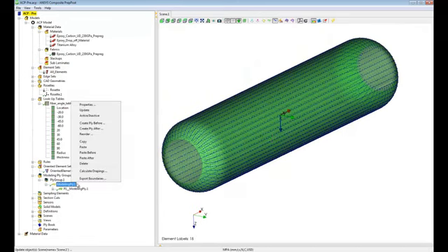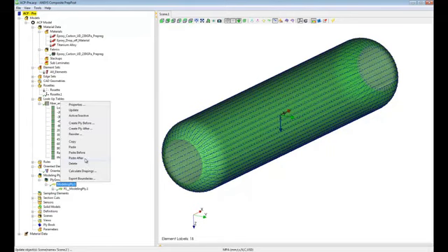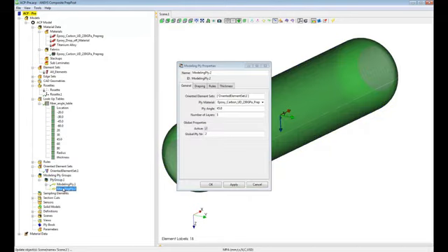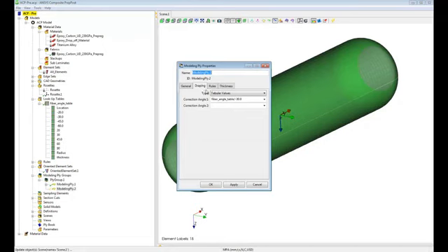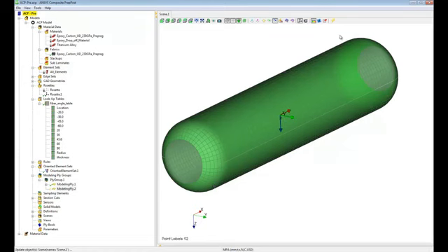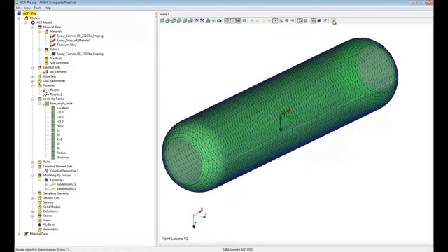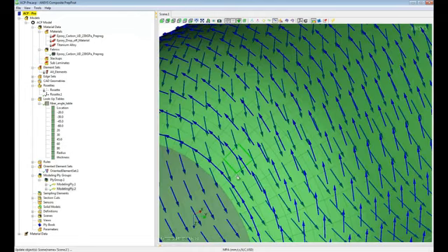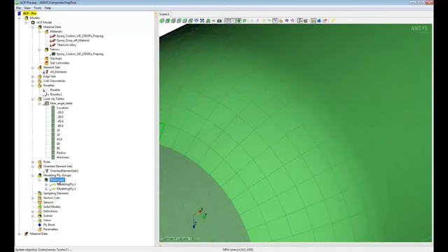Let's now move on to defining other plies. We can copy an existing ply, put it anywhere after, before, so you can manage the sequence of your plies. And we are going to choose for this second group another part of the table. And again, we update, we see a different orientation here on the model. So again, all the plies you will define can be defined using either direct angles or the tables as we've shown in the two previous examples.